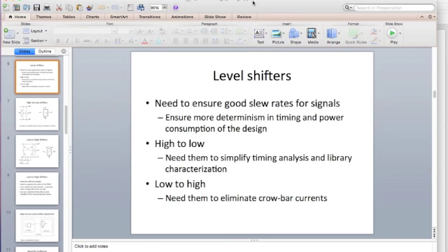The exact amount of fluctuation will be given by the slope times the voltage noise, or depending on what units we are defining the slope in, it's related to the slope and the voltage noise. So the timing noise is proportional to the voltage noise as well as the inverse of the slope. Because of that, you need to ensure that you have good slew rates.